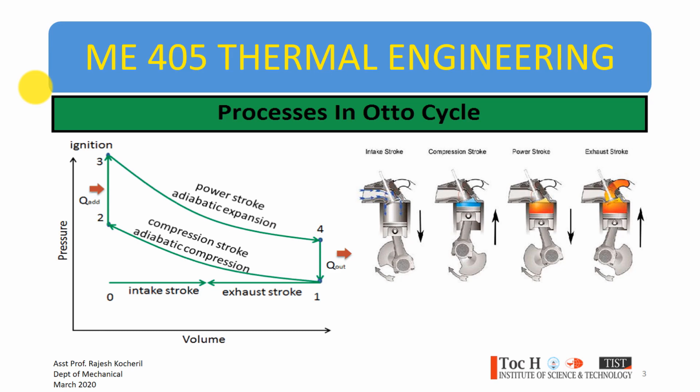At this time both inlet and exhaust valves are closed. Then subsequently, when the piston is about to reach the top dead center, the spark plug which is provided in the cylinder will initiate a spark, and subsequently this spark propagates into the mixture and ignites it.